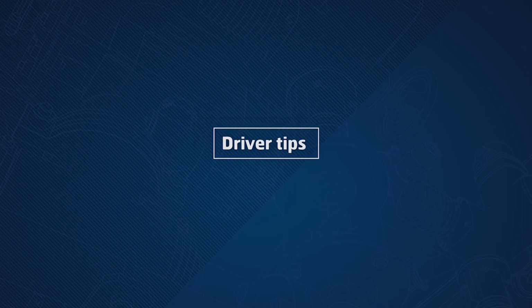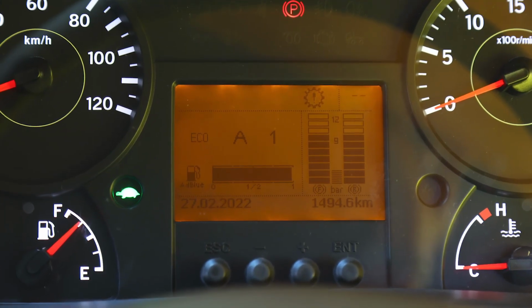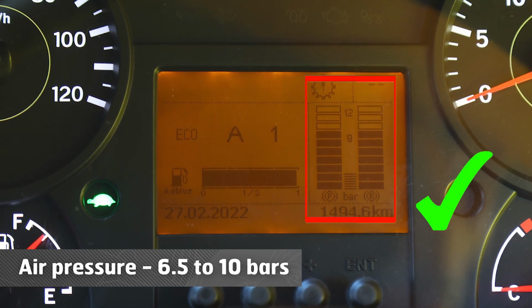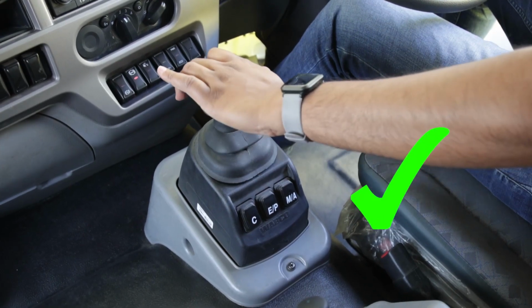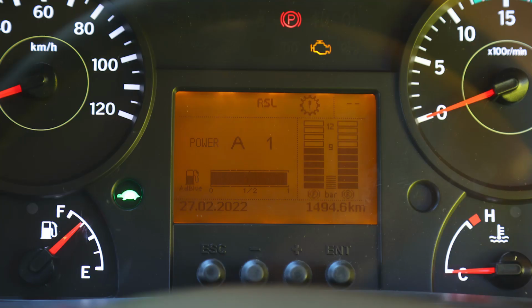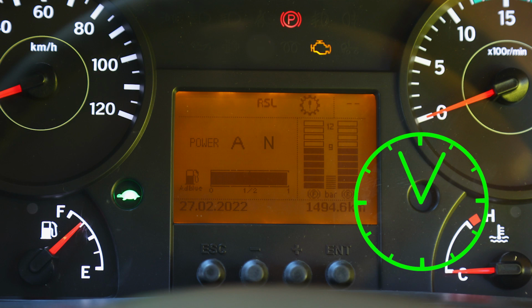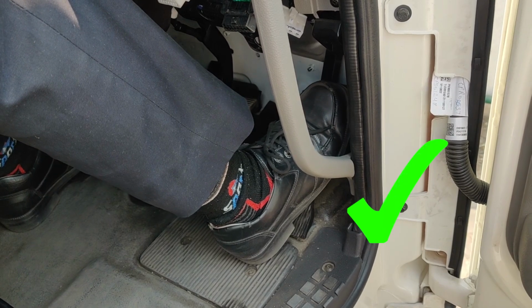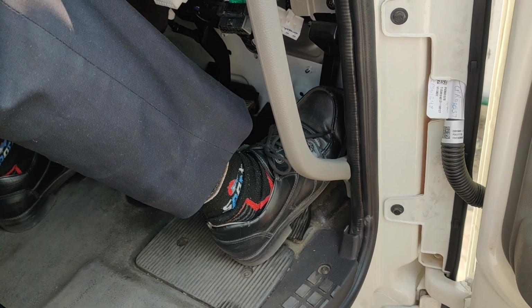Driver tips. To operate AMT, pneumatic pressure should be between 6.5 to 10 bars. Operate the joystick gently. AMT will automatically shift to neutral after 120 seconds in idling. To avoid this in traffic, slightly press the accelerator pedal once.